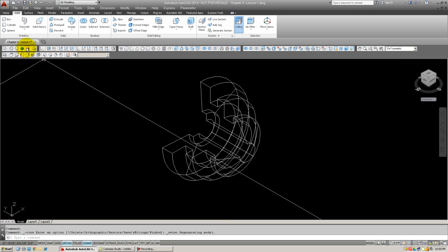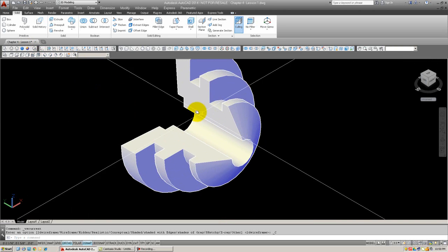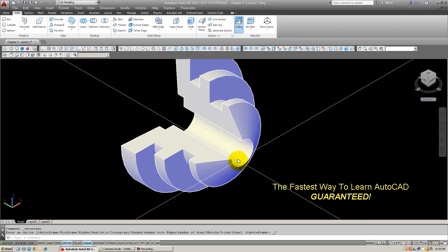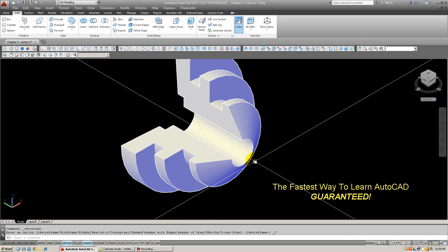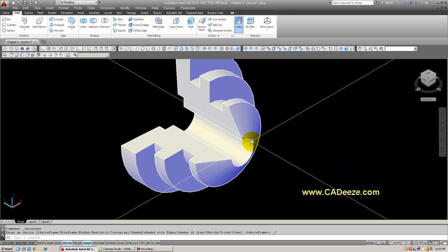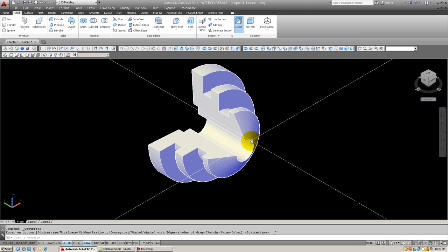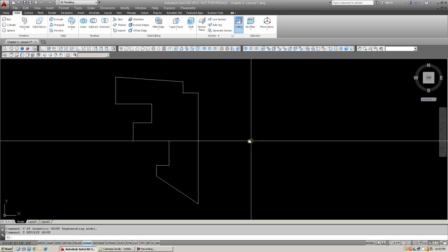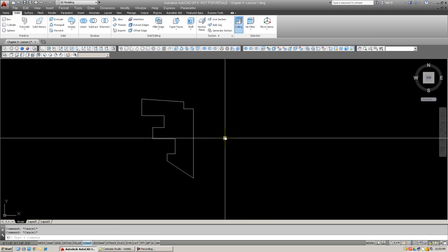and as I switch to 3D, take a look what happened. Our object now has a gap in it, a hole. And that hole is exactly twice the distance that you offset your axis of revolution from the part. Obviously it rotated around that axis, so the hole will be twice as big as that distance. So that is how you create holes in objects. Okay, and one more demonstration has to do with positioning of this axis of revolution. I'm going to do revolve again.